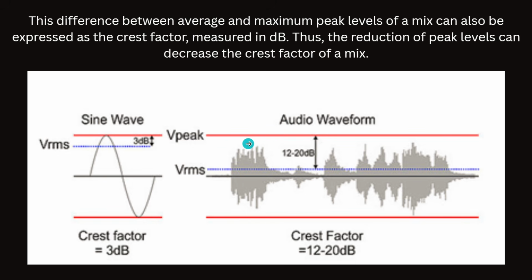It's important to understand. We can't measure those China boards, or any manufacturer's Class D boards, at a maximum sine wave, because those are not built for that. Those are built for audio, and thermally they can sustain audio. They can perfectly operate with an audio signal, and really are capable of handling all those peaks in a perfect way, but they can't remove heat if you use a sine wave at the peak level.